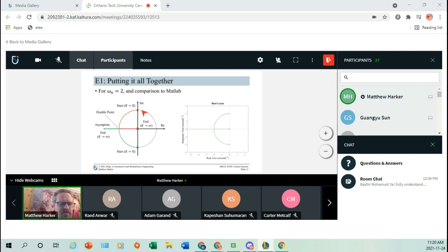Right, you have these branches here that from the equations we know have to be on a circle, just from the formulas. But of course, if we have higher order systems, we're then just sketching the curve based on whatever knowledge you have of cubics and higher order curves. That's not really precise, but at the key points, these rules are picking up the key points, right?